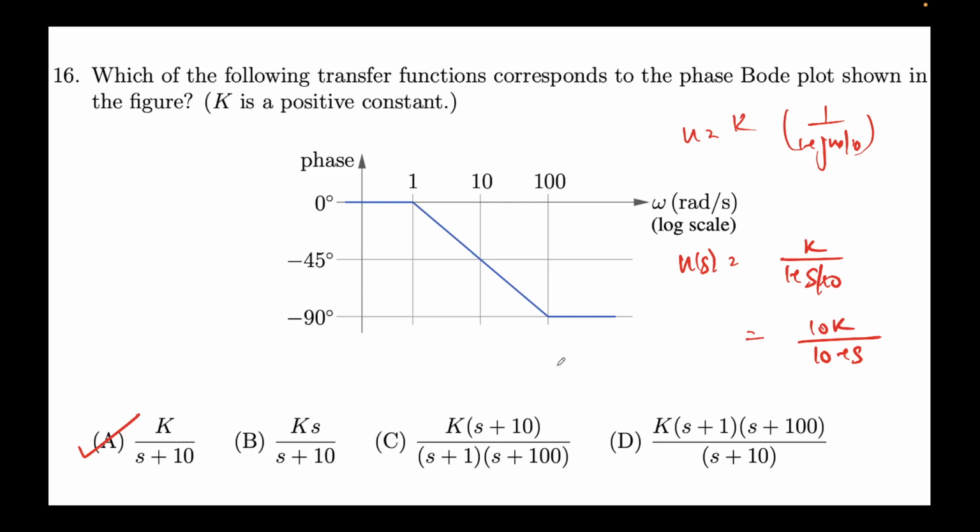So just to summarize, in today's class we talked about what happens when we introduce diodes to op-amp. So how the diode is on and off, and how the output waveform may look in terms of the input, that we saw. And then finally we solved quite a few problems on magnitude Bode plot and phase Bode plot, both flavors. That is, you are given the transfer function and you are required to plot the magnitude and phase Bode plot, and vice versa. That is, you are given the plot like in this problem and you are required to find the transfer function.